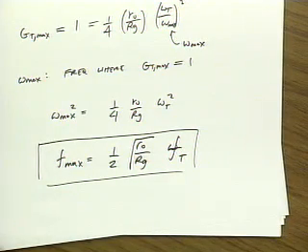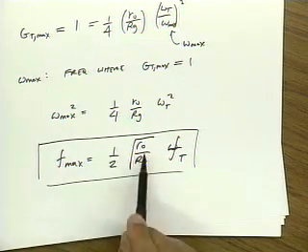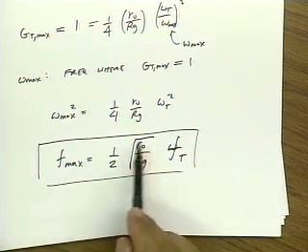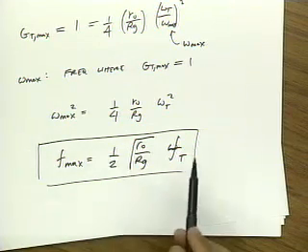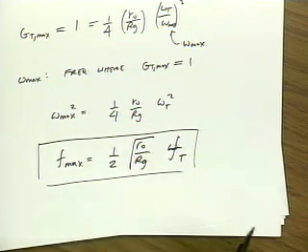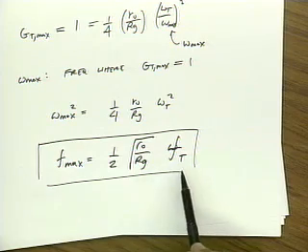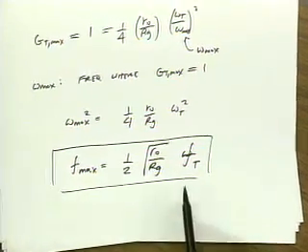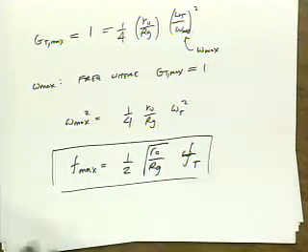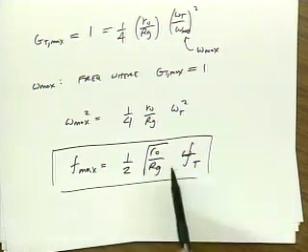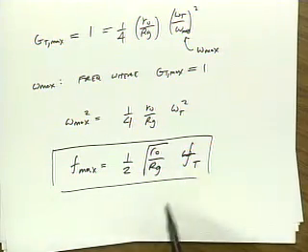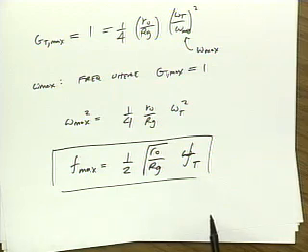So under the simple approximation that we made, a unilateral device, we can see that as long as I can maximize the ratio of the output impedance of the device to the gate resistance, I can go up to really high frequencies. In particular, you can even go higher than Ft. Whereas Ft characterizes the bandwidth of a wideband system, in an RF, narrowband system Ft is not that relevant because I can always tune out my parasitics. But I can't do that at an arbitrary frequency.